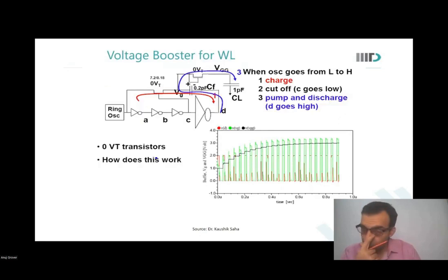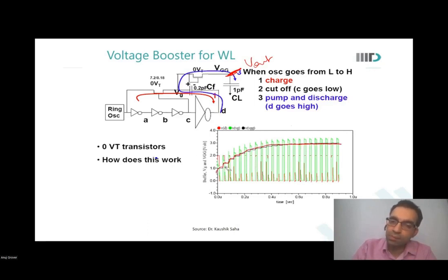Let us look at it in terms of a time series. So that was just one step, and you may have felt that VDD directly becomes 2 VDD. Doesn't really happen like that. In reality, when the charge pump starts to operate, the voltage VGG over here, which we say is the V output voltage, would see this kind of a stepped increase, and then almost becoming stable. The black curve.